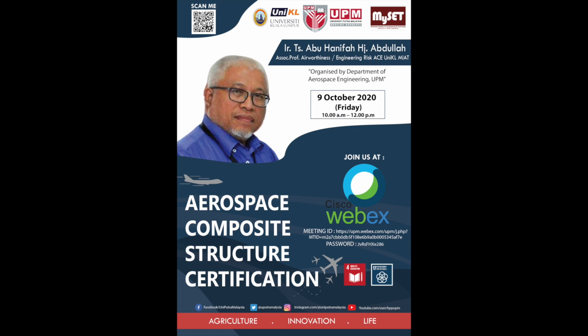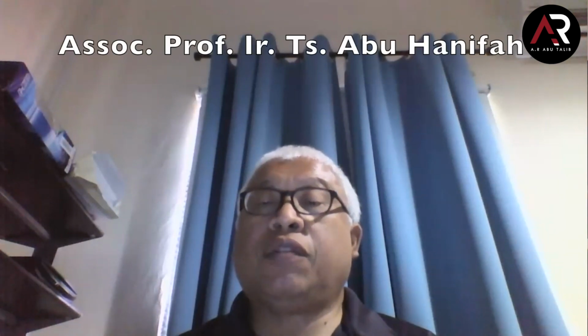Okay, since the A350 and 787 are a composite airframe type, I see there's no limit of validity available in the FAR. So basically, our question is: these airplanes are already in service for quite a few years. So in terms of this LOV and also the aging aircraft safety rule, how are these airplanes complied with? Okay, I believe from my understanding of FAR 26 or CS26, that is for the aging aircraft. So the 787 and A350 are new aircraft, even though they've been around for many years. But I don't think they fall into the category of aging aircraft yet, because FAR 26 and CS26 were published after they realized this aging aircraft is an issue, and we need to have the aging aircraft program.